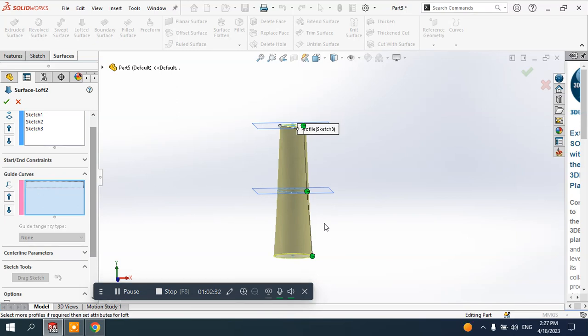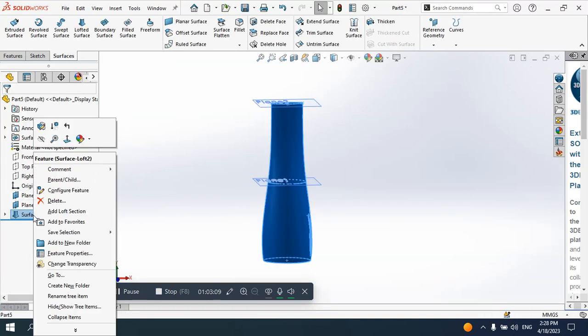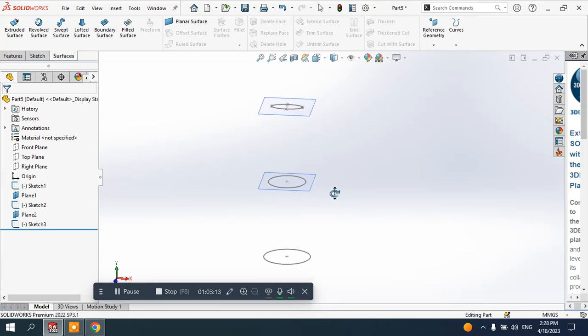So if you look here, that outer shape is just a straight line, which is just combining with the straight normal to these profiles. But using the guide curves, we can create more complex shapes and control here the outer shape as the requirements and the shapes and so on. In order to do this, we need to create obviously the guide curves for the other planes. We can create one guide curve, two guide curves, 3 and 4 as a maximum. So let me firstly just delete this surface element, keeping these three profiles. Let's firstly create the guide curve.